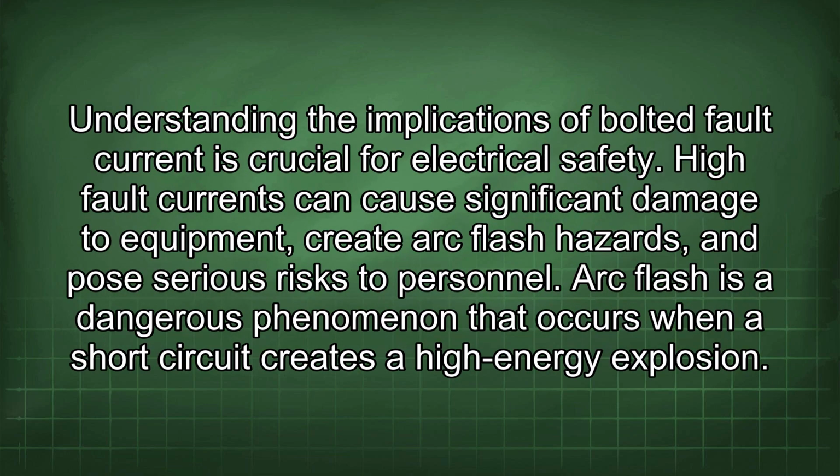Understanding the implications of bolted fault current is crucial for electrical safety. High fault currents can cause significant damage to equipment, create arc flash hazards, and pose serious risks to personnel. Arc flash is a dangerous phenomenon that occurs when a short circuit creates a high-energy explosion.